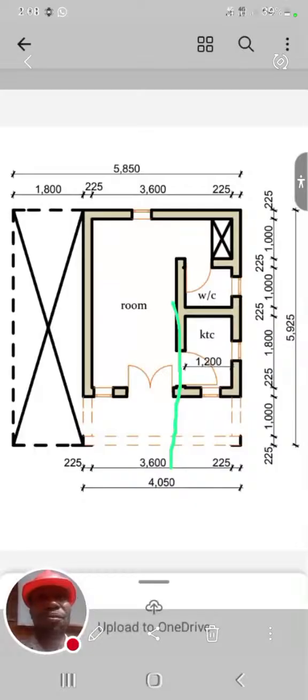If the real project is very big, very massive, how are you going to select the scale you are going to use? You are likely going to use 1:500 or 1:1000, so that you can draw the massive project very well and it can be contained on a paper.